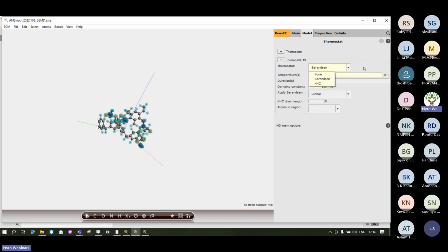In this specific case, we need to correct the ensemble and the approximation from the shorter damping time. In this crucial step, we need to set the damping time as high as practical to reach the target value in an acceptable time. That's why we have selected this thermostat instead of NHC. For the NHC thermostat, the simulation samples the correct ensemble no matter what damping time is set, but we recommend setting a damping time which roughly corresponds to the correlation time of the system. So when we go for these bulk polymerization steps, we need to select this Berendsen thermostat.